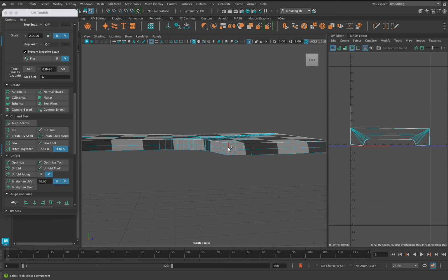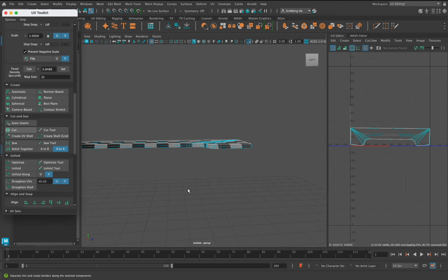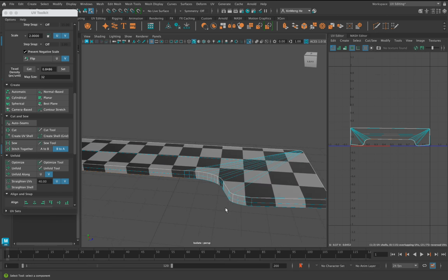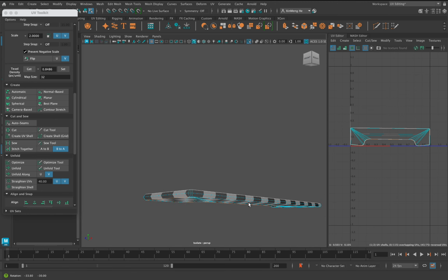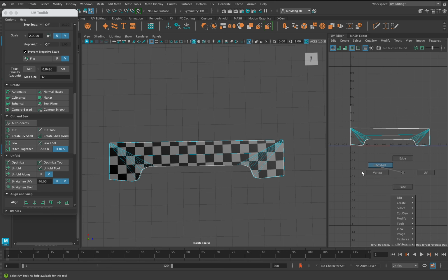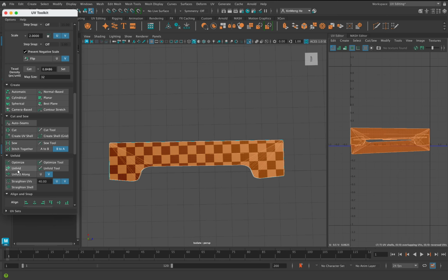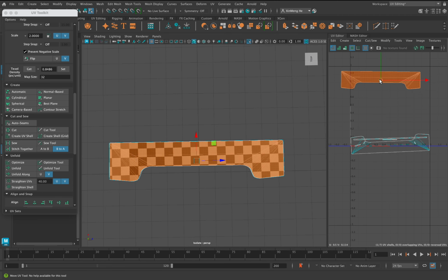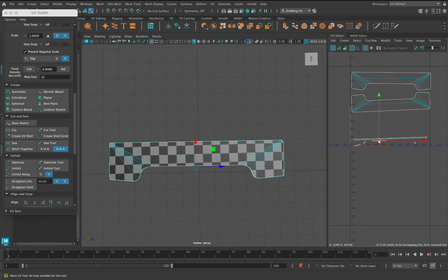After unfolding, you'll see 4 rectangles of varying lengths. For the lower half of the table, repeat the previous steps by selecting the edges and cut them. Hold the right mouse button to enter UV shell mode, then select all and click on Unfold. When we unfold, move each of these shells apart, rather than laying on top of each other.